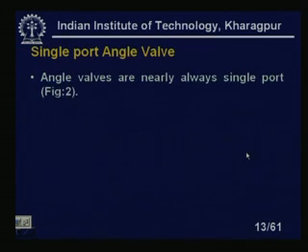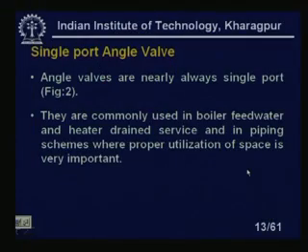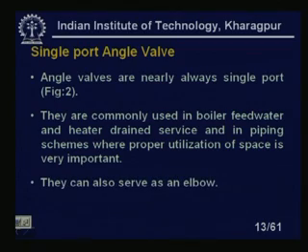Single port angle valve. Angle valves are nearly always single port. You will see that it is in an angle, like an elbow. They are commonly used in boiler feed water and heater drain service, and in piping schemes where proper utilization of space is very important, because we cannot always use just a linear pipe. When I need a bend, we can use a single port angle valve. They can also serve as an elbow. So instead of using an elbow, I can use an angle valve, which will make the flow control as well as save an additional elbow in the process pipeline.